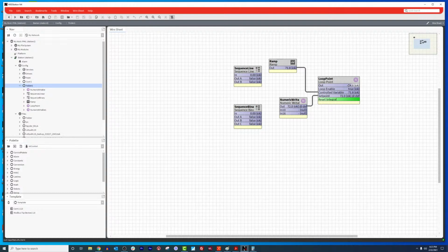This is why in most cases I will not use derivative, because if you don't get it right, you're going to have a crazy high oscillating loop. Your loop's going to go boom, boom, boom, up, down, up, down. It's crazy. So I try to avoid that. Nine times out of ten, if I can get my proportional dialed in and my integral dialed in, then I'm good. I don't need that derivative.